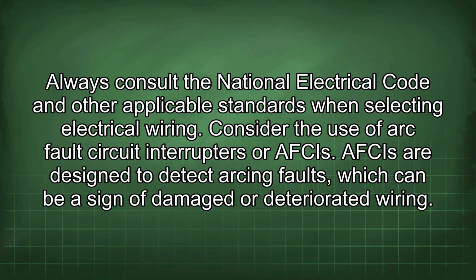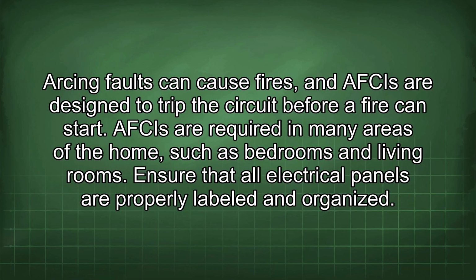Consider the use of arc fault circuit interrupters, or AFCIs. AFCIs are designed to detect arcing faults, which can be a sign of damaged or deteriorated wiring. Arcing faults can cause fires, and AFCIs are designed to trip the circuit before a fire can start. AFCIs are required in many areas of the home, such as bedrooms and living rooms.